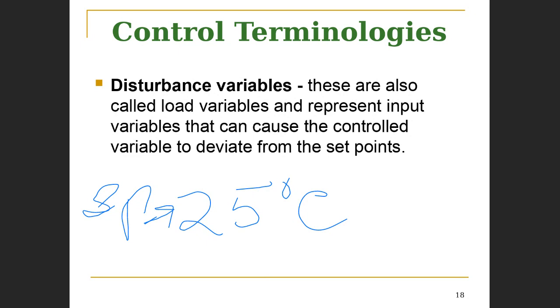All right, so I get that. You're going to have a greater portion of hot water mixing with a lower portion of cold water. So it will certainly be hotter. I understand, sir. Right. So that's the type of disturbance that we're speaking of. So the flow rate of the cold water is a disturbance to you maintaining your suitable temperature at the faucet. So the point I'm making here is the flow rate of water in any of those pipes, hot or cold, is a disturbance variable.